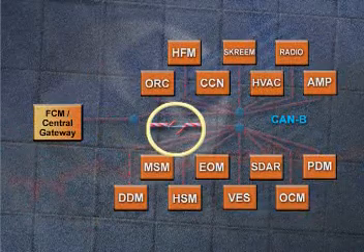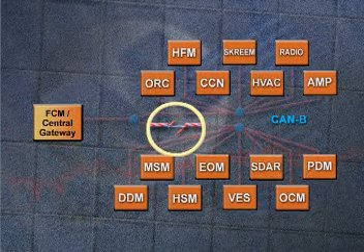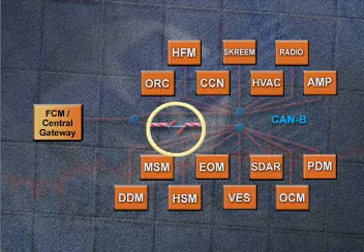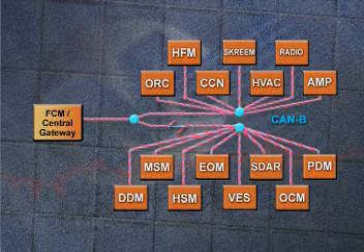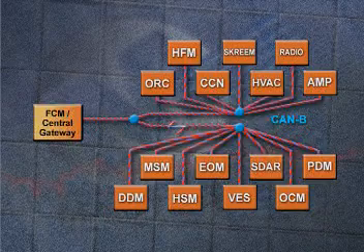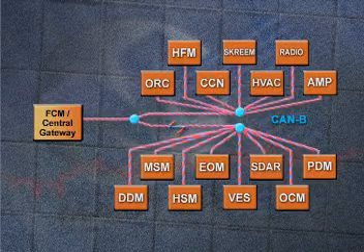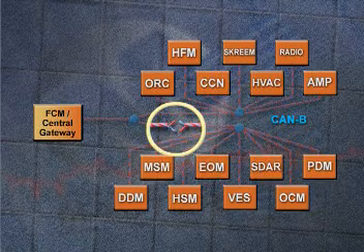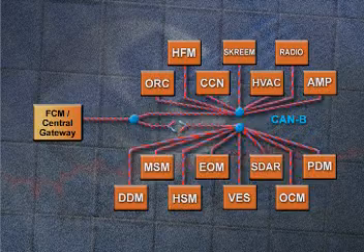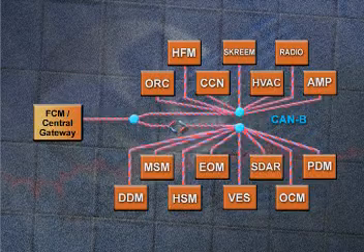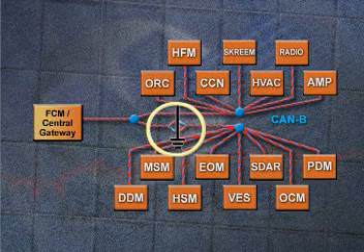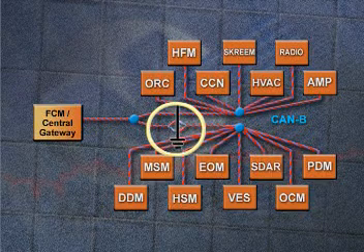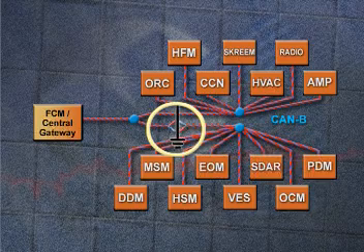When it comes to malfunctions, the CAN-B bus is more fault tolerant than the other CAN buses. In fact, if a condition only affects one wire, or if both wires are shorted together, the bus can continue to operate in a single wire mode. In this mode, the bus may not perform as well as with both wires functioning normally. If both wires are open, bus messages may also get through depending on the location of the break and the modules involved. More serious conditions, such as both wires shorted to power or ground, can cause the bus to stop communicating.